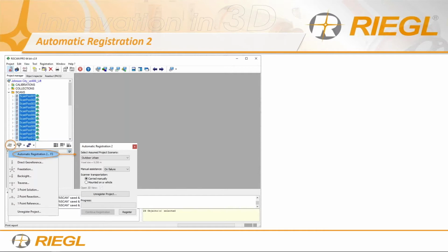And then it asks you if you're carrying it on a manual tripod or mounted on a vehicle. Please select the right one. If you're on a tripod, you don't want to select mounted on a vehicle, right? The reason why we have the two is because when you're mounted on a vehicle, it assumes that the vehicle will project a large magnetic error on the digital compass, right?